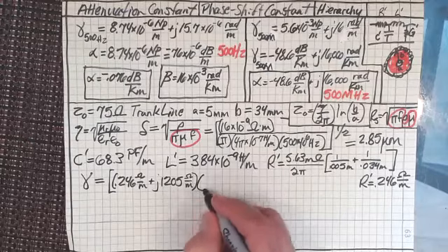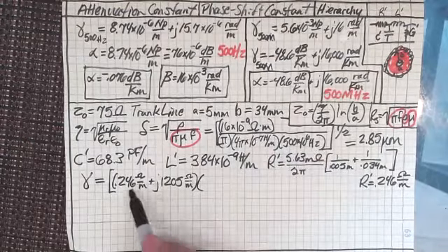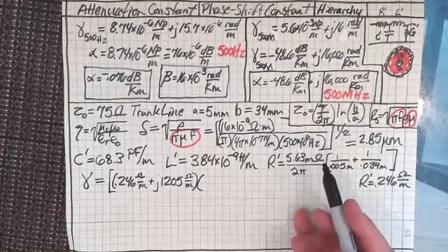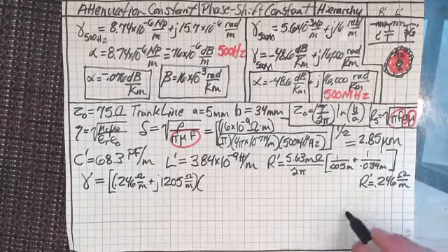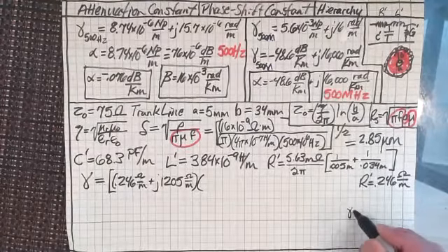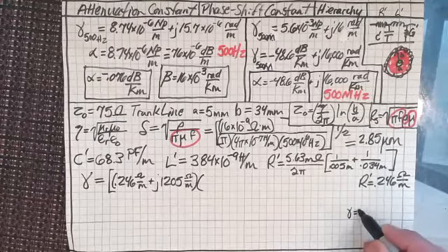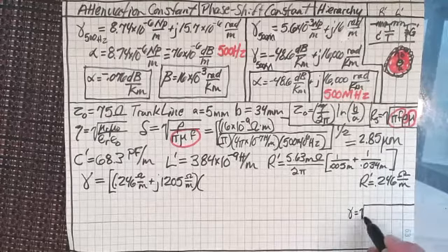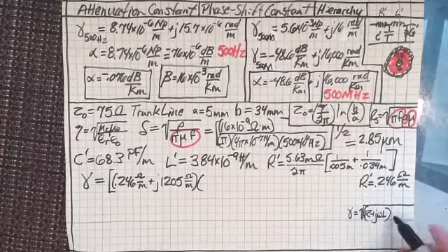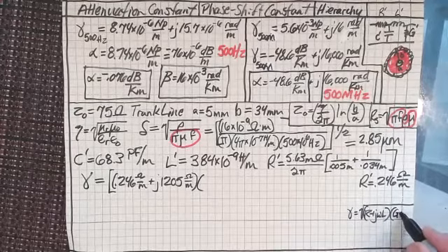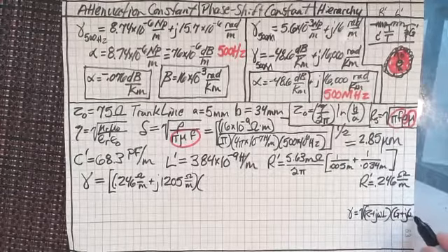And then let's multiply that. Now we know G. So this times G plus J omega C. I probably should write that out someplace down here. Gamma equals the square root of R plus J omega L times G plus J omega C. Everybody has this anyway.